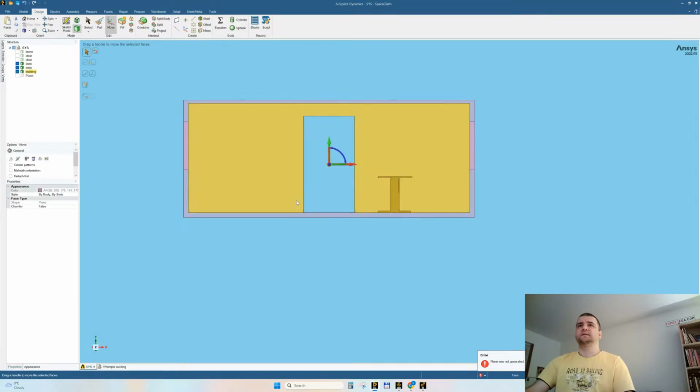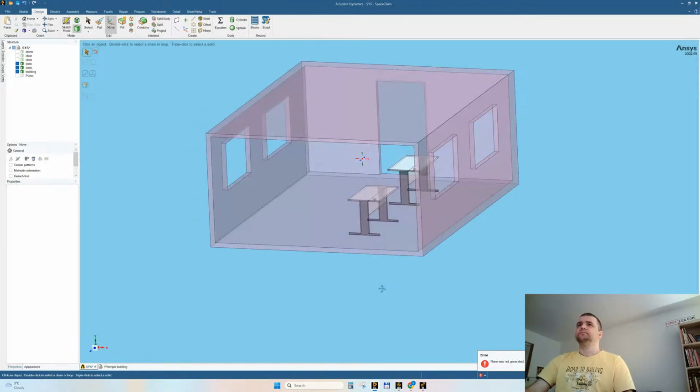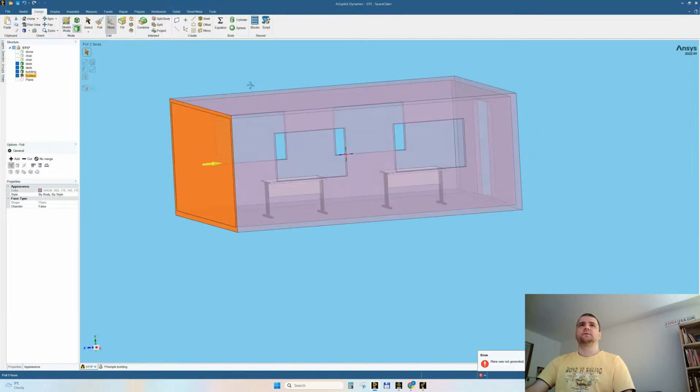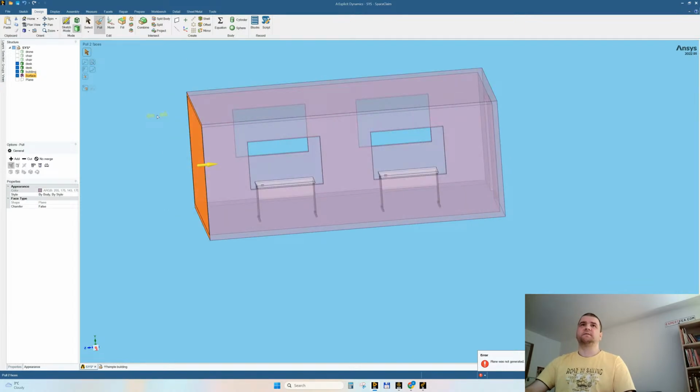Let's move a little things. What we have here. I selected the door frame, door cutout, because I would like to move what we have here. Maybe something like this. All right, let's create a wall, fill, and I will select these two surfaces -70.